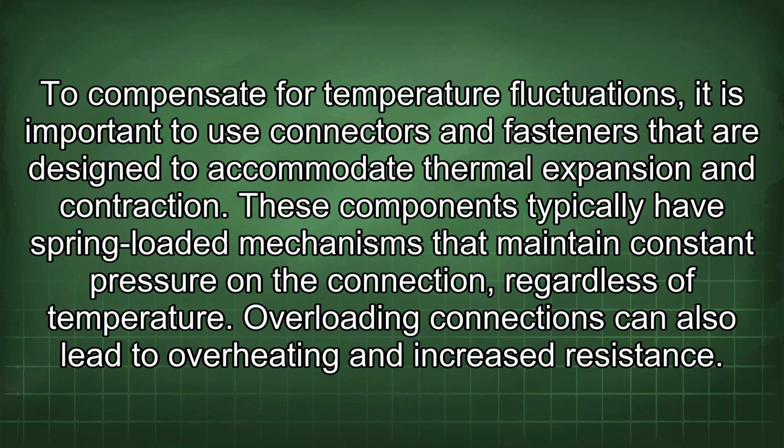To compensate for temperature fluctuations, it is important to use connectors and fasteners that are designed to accommodate thermal expansion and contraction. These components typically have spring-loaded mechanisms that maintain constant pressure on the connection, regardless of temperature.